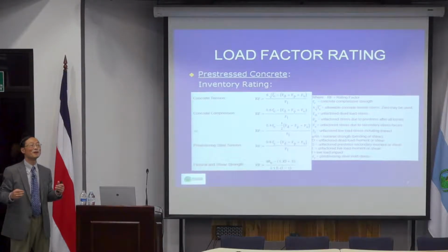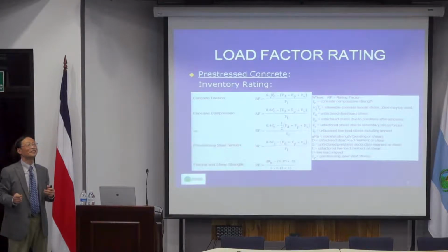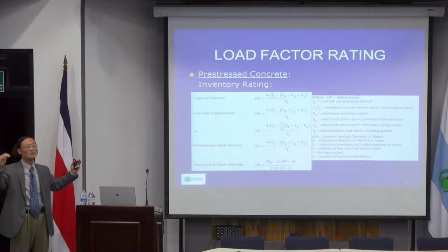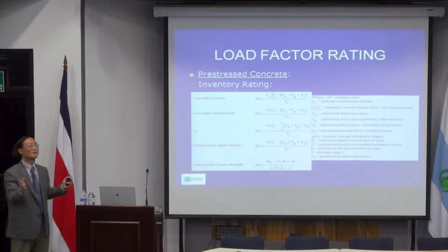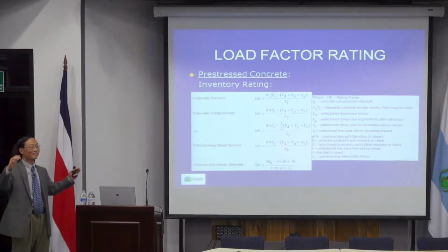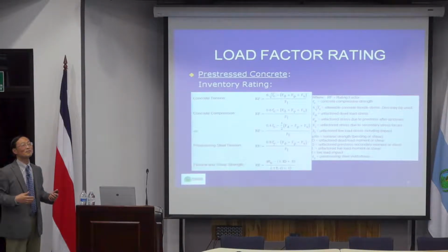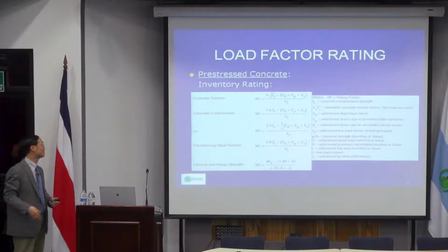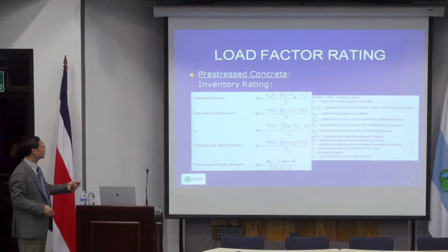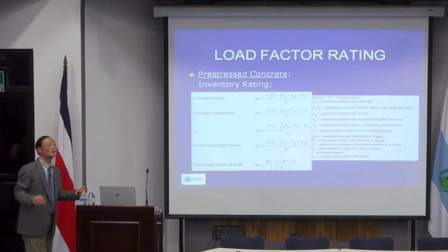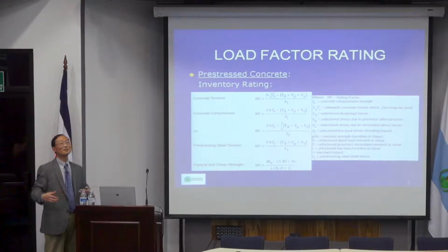It's not imaginary. And actually, if you look at AASHTO, the only load factor which is 1.0 is for secondary stress, because that is mathematically determined. There's no distribution of any type, so that is certain for certain bending moments. We have a load factor of 1. Every other has distributions, so we have different load factors for different things. So altogether, we call these three components permanent stress. Permanent stress is just like dead load. You cannot do anything about it.